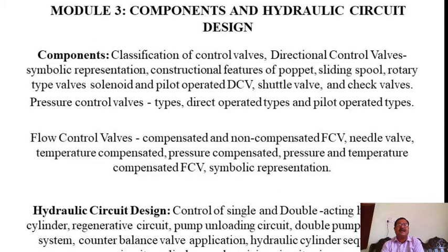So in the hydraulic circuit the hot fluid is moving, and the hot fluid will have some temperature. That temperature should be handled very well. To handle that temperature, we use these temperature compensated flow control valves. There are also pressure compensated only, and pressure and temperature compensated combination flow control valves, and the symbolic representation will be there.